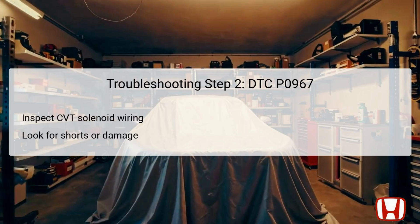The second step in diagnosing DTC P0967 involves inspecting the wiring associated with the CVT-driven pulley pressure control solenoid valve. This inspection should be thorough, checking for any signs of wear, fraying, or potential short circuits is crucial. Technicians should focus on the wiring harness as well as connector terminals, as these areas are vulnerable to damage due to their location within the engine compartment.